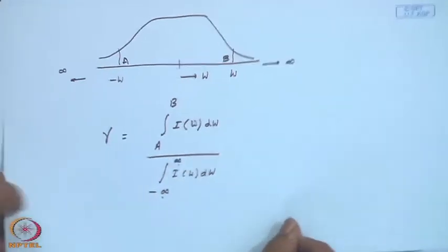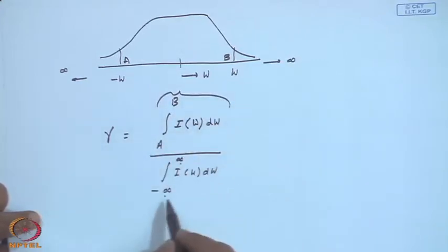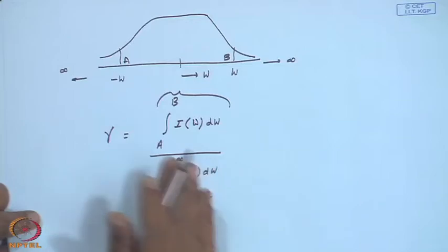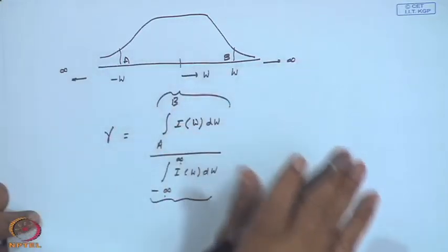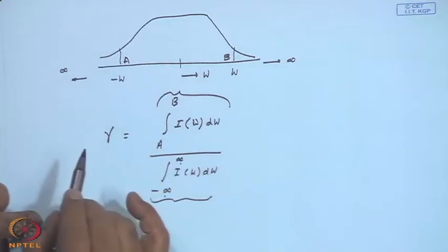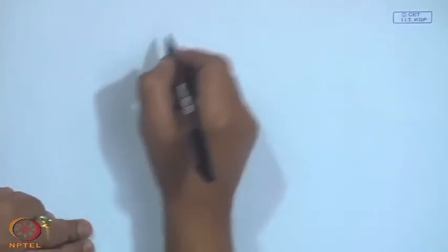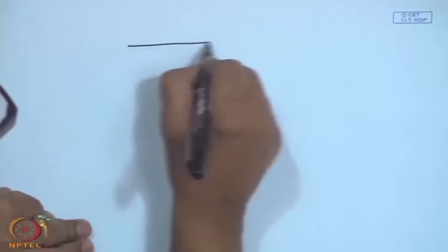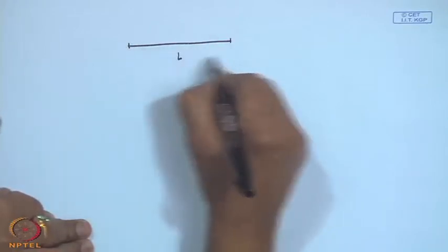Okay. So, this is the radiation intercepted by the receiver, and this is the radiation that technically got reflected up to and including infinity, and if I find out the ratio, I will have the interceptance factor. Now, some clarification is required. Instead of that, if I have got some L as the receiver width,